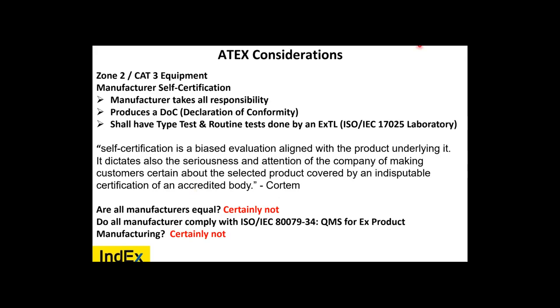So be aware there is a difference between ATEX and IECEx. IECEx equipment, Zone 2, Gc equipment, is certified, independently third-party tested and certified. ATEX, there's a weakness in the system there.